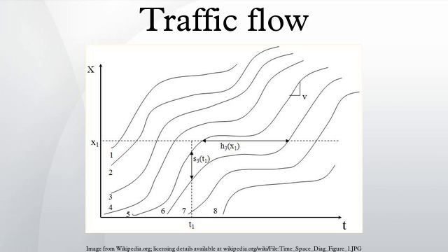Kerner's network breakdown minimization principle. Kerner introduced an alternative approach to traffic assignment based on his network breakdown minimization principle. Rather than an explicit minimization of travel time, which is the objective of system optimum and user equilibrium, the BM principle minimizes the probability of the occurrence of congestion in a traffic network. Under sufficient traffic demand, the application of the BM principle should lead to implicit minimization of travel time in the network.